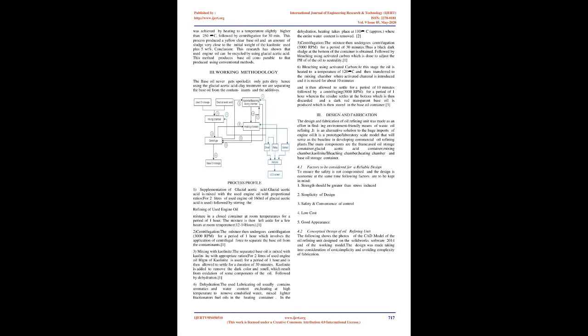Acid treatment: 300 ml of used engine oil was measured in a 500 ml beaker. Also, 30 ml of sulfuric acid was measured in a separate 50 ml beaker. The regulated hot plate was switched on and the measured used engine oil was placed on top. The temperature of the used engine oil was maintained at 40-45°C. At this temperature the sulfuric acid was introduced into the used engine oil with simultaneous stirring of the mixture for 10 minutes.